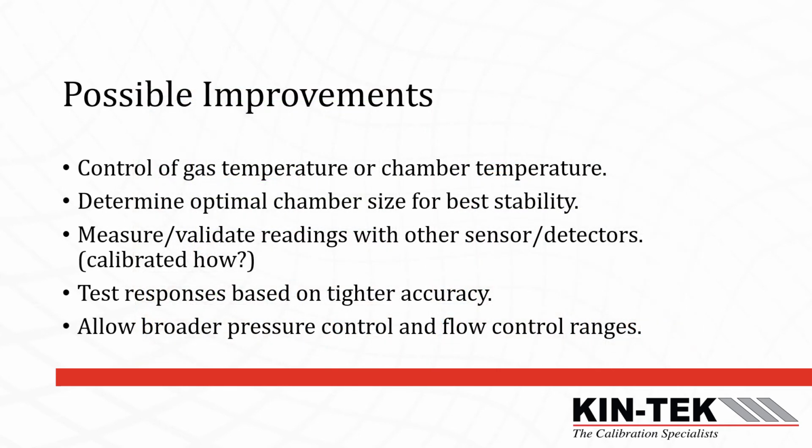Okay, I've shown that we can create a gas mixture from the FlexStream permeation system and apply a variable percent RH at different step changes. And we can do that for stabilizing a concentration and delivering that concentration and the percent relative humidity to a device under test. But some of the possible improvements that we need to consider are controlling the gas temperature or the chamber temperature. So whether it's going across a sensor block or going into a chamber, that gas temperature does play a role when it hits that external sensor in the feedback controls that it does with the FlexStream system.